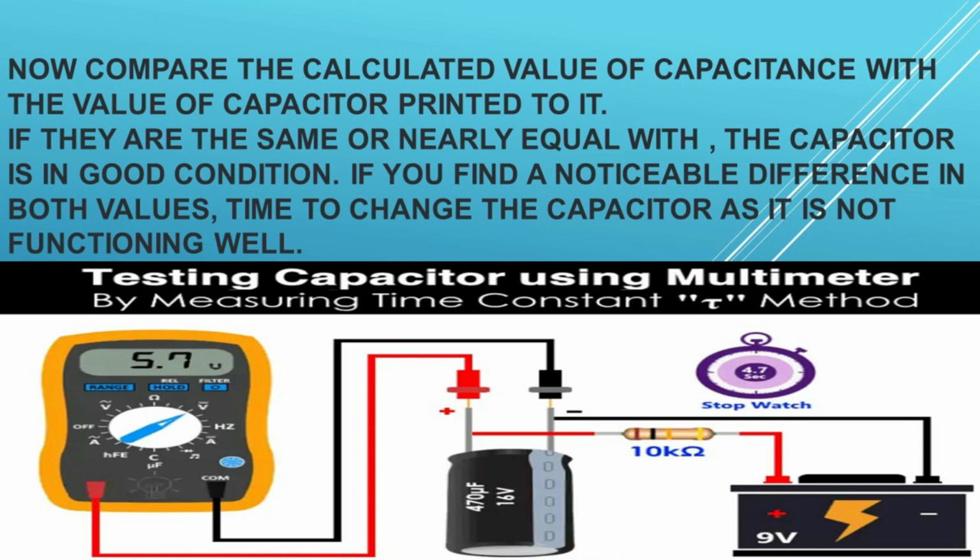Make sure to connect the positive, red, lead of the voltage source to the positive, long, lead of the capacitor and negative to negative. If you are not sure or unable to find the proper leads, here is the tutorial on how to find the negative and positive terminal of a capacitor.